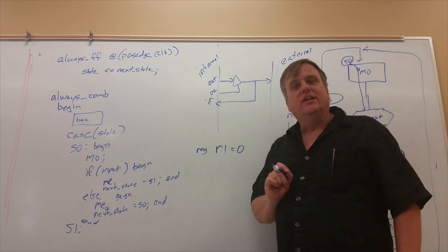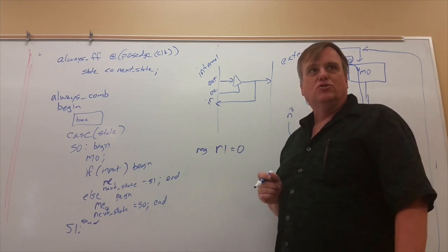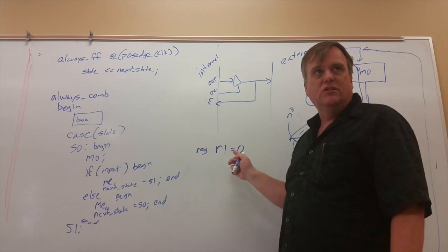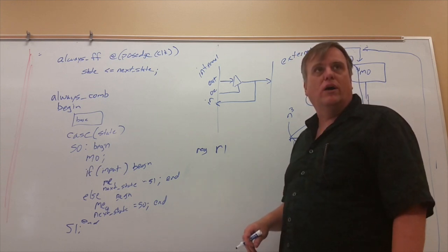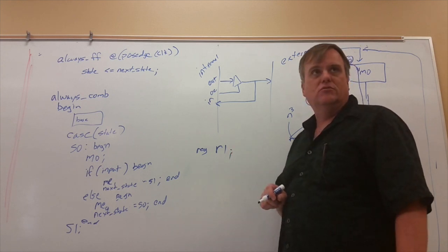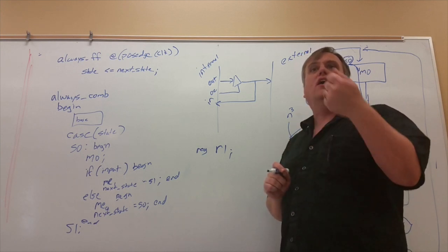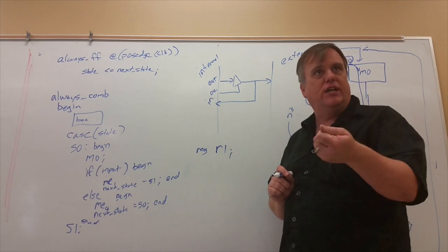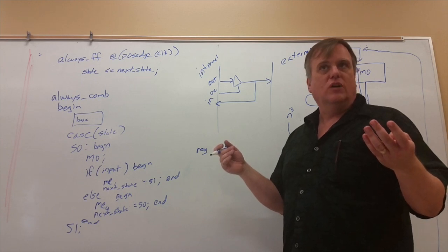So this is not a good synthesizable format. This is good for simulation, but it's not particularly good for actually doing synthesis. A better way to do this, so you know what you're going to get, is to not do that, and instead create a global variable, let's say like run. Run is set to 1 when the system is running. It's set to 0 during boot or things of that sort.